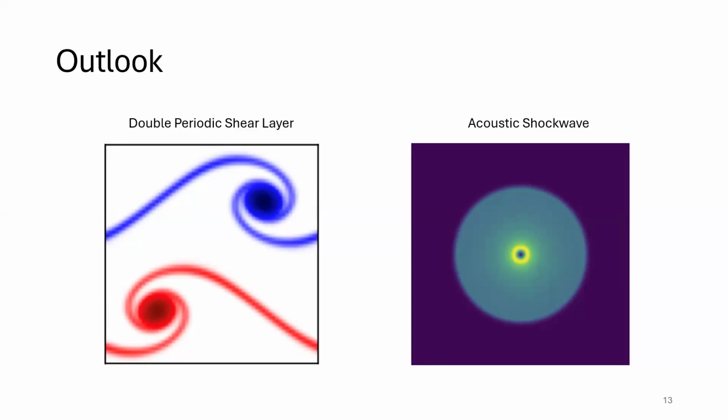So everywhere where you got some symmetry, even though it is a highly symmetric flow like the Taylor-Green vortex or a low symmetric flow, I would call it, like the double periodic shear layer, it should be possible to use these symmetry boundary conditions.